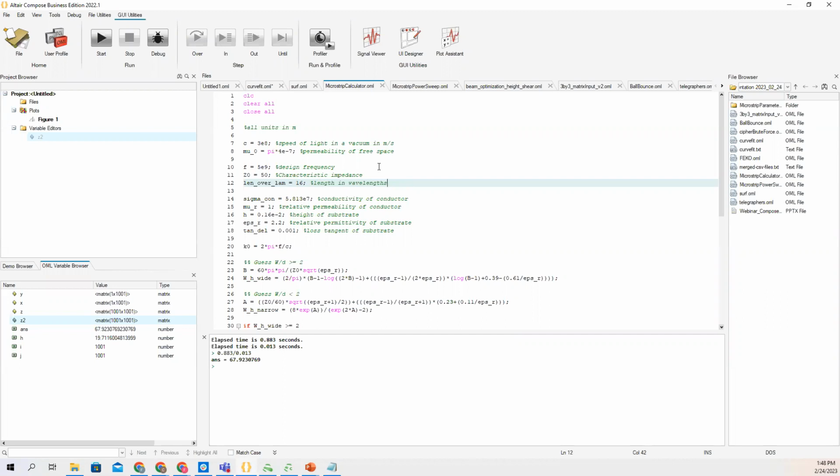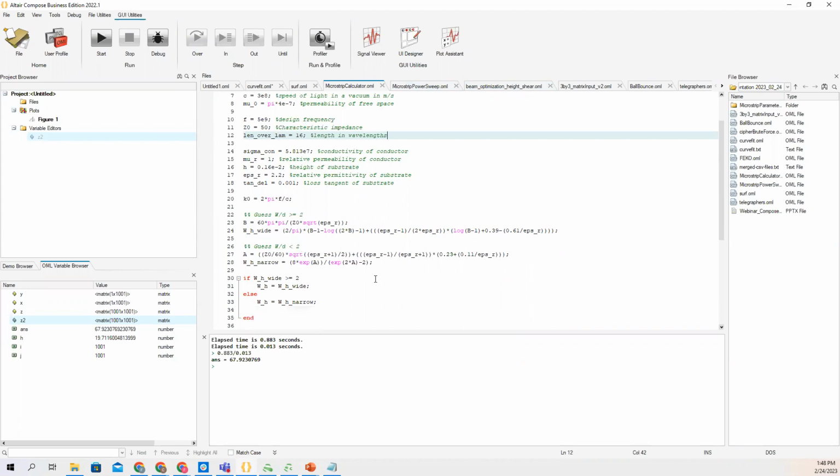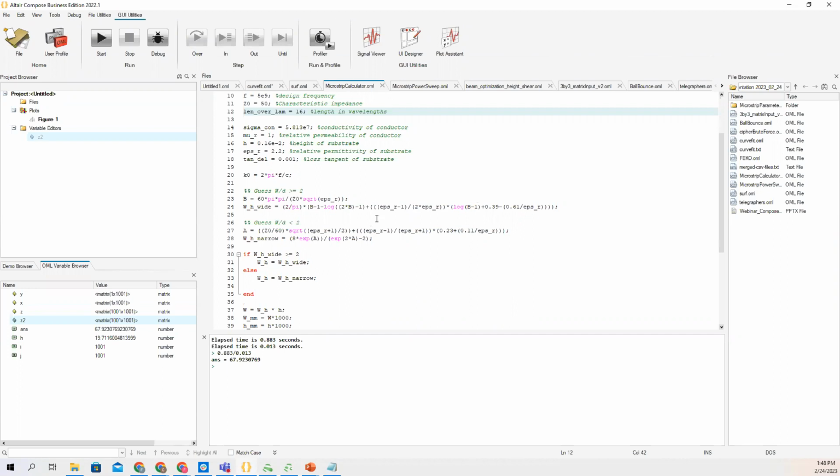Then you have to calculate your effective dielectric constant, your wavelength, surface resistance, your attenuation in the conductor and in the dielectric, and then of course convert all that to decibels, because that's probably what you're most interested in. And again, I apologize if you're not an electrical engineer, but to make a long story short, there are a lot of steps. Anytime you change one parameter, there are a lot of calculations you have to go through, including this big nasty one that could change based on which parameter you use. So you're not guaranteed to use the same equation every time.